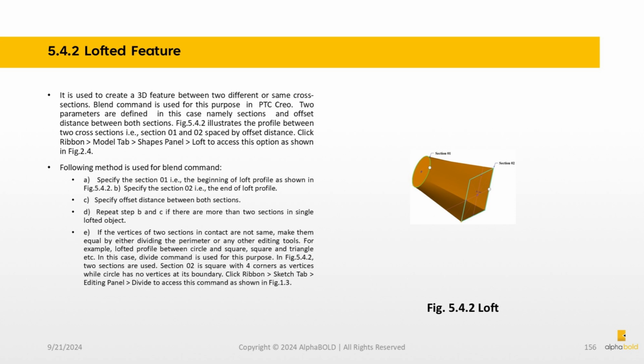Draw the circle of spring wire diameter D at one end of the straight line where two construction lines intersect each other. D. Specify the pitch P or number of turns N of the spring. It has the following equation: P equals 1/N. E. The resultant helical spring will be modeled.